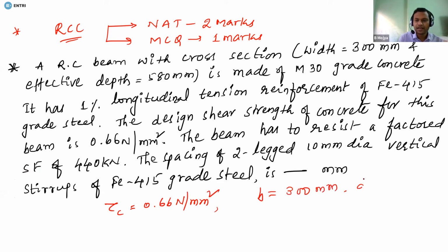And remember, whenever it is not specified whether the depth is effective depth or overall depth, if it is simply given as depth, then you have to treat it as effective depth only. If it is given total depth and there will be clear cover or effective cover, then in that case you will have different terminology. But fortunately, in this question, it is given directly as the effective depth, so don't worry about it.